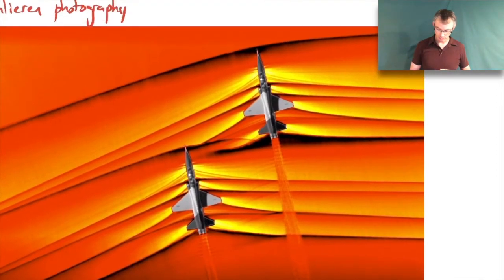So you'll see situations, if you're going faster than the speed of sound, you can get a shock wave that forms. You can also get what's known as choked flow when you discharge vessels. So a choked flow is if you pressurize a container, let's say a big gas container, and you discharge it to the atmosphere. A choked flow is where even if you change the back pressure, the pressure that the tank is discharging into, you can't make the flow speed up anymore.